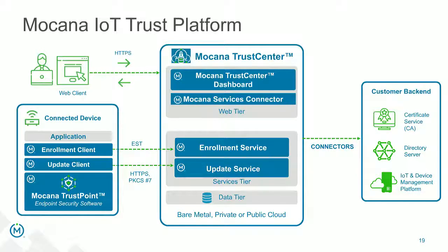Yes, we do have a mutual authentication method, and this is done with certificates. So when an update client establishes a connection to the update service, there is a mutual authentication at that level. In addition to that, there's another level of security where the update packages are encrypted with the device certificate. So even on your journey back from the service to the device, there is a process to make sure that that package cannot be abused by the device without actual possession of the private key.